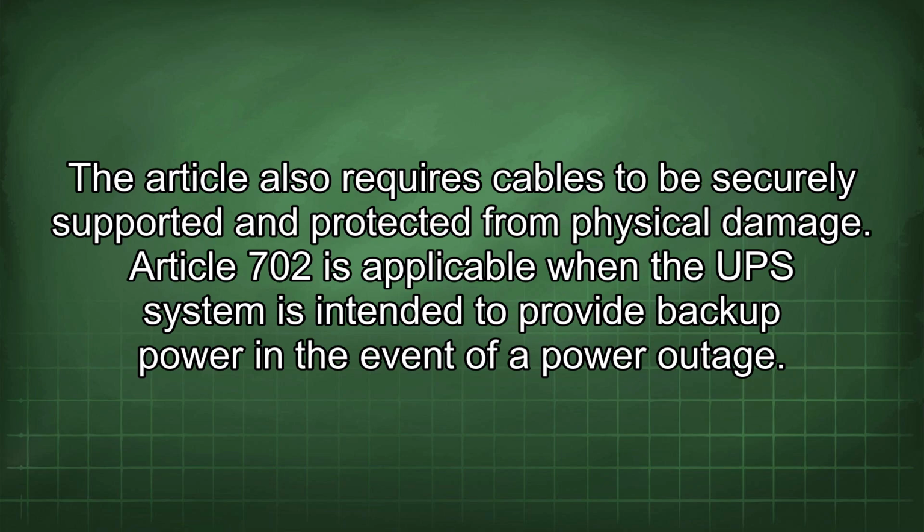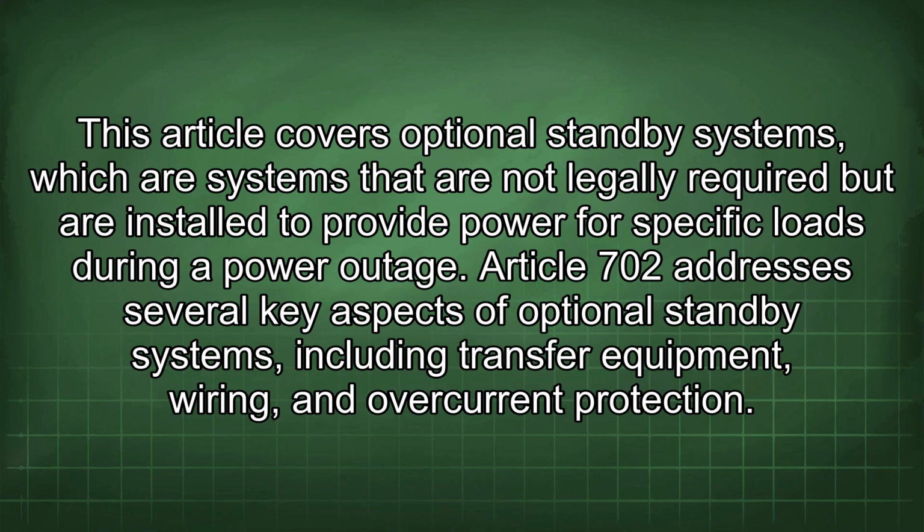Article 702 is applicable when the UPS system is intended to provide backup power in the event of a power outage. This article covers optional standby systems, which are systems that are not legally required but are installed to provide power for specific loads during a power outage. Article 702 addresses several key aspects of optional standby systems, including transfer equipment, wiring, and overcurrent protection.